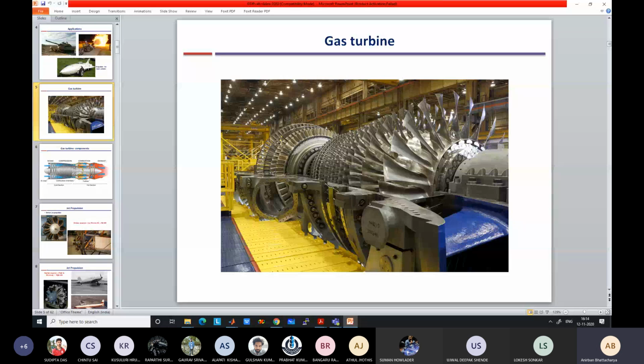What about the stresses that are generated in the blades? Whenever I ask any of these questions, the first consideration is the blades, because blades are the costliest part of a gas turbine. Blade materials are particularly for turbines. What will happen if you keep on increasing the number of stages? The first stage will have very small blades and the last stages will have very large blades. Both for compressor and turbine, a similar thing is happening.